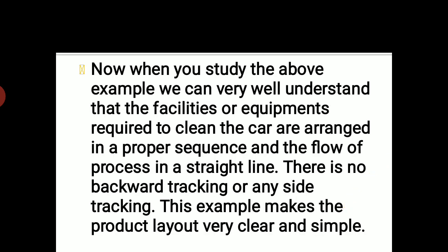Now when you study the above example, we can see very well and understand that the facilities or equipment required to clean the car are arranged in a proper sequence, as I told you, and the flow of process is in a straight line. There is no backward tracking or any side tracking. This example makes the product layout very clear and simple.